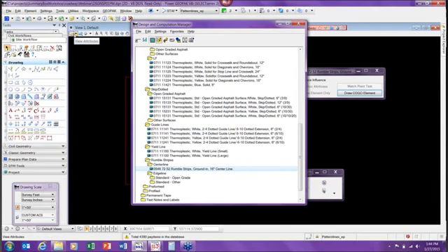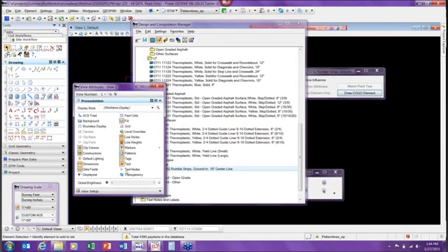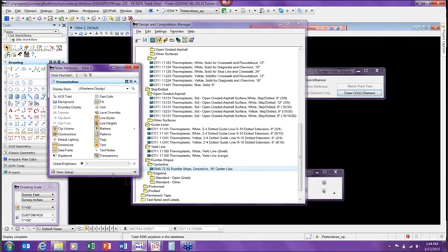And if you go into your view attributes up here and enable transparency, we've set that to a transparency of 70 so that it goes out behind everything. It's not glaring, so that whenever you go to do your yellow striping down your center line, you can see very clearly, even if that is still turned on back there for the rumble stripe, where your markings stop and start in your center line.